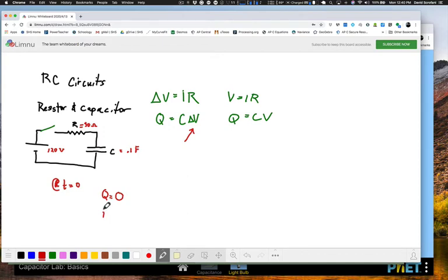What's the current in the resistor I at that point in time? Well, as I said before, at that moment in time, the voltage drop right here across the resistor is 120, only for that instant. And therefore, with a 30 ohm resistor and 120 volts, I wind up with a 4 amp current initially, like so.